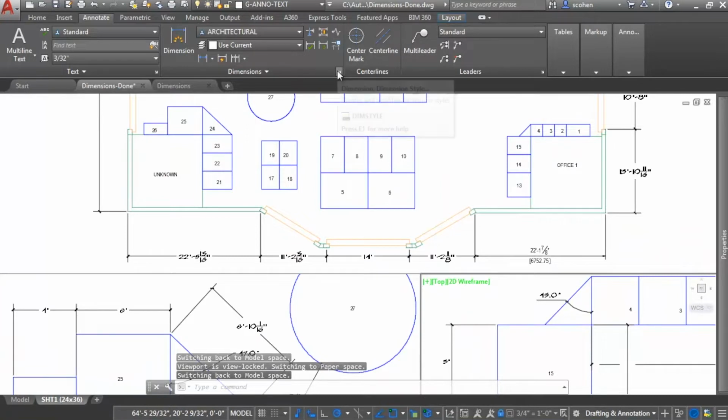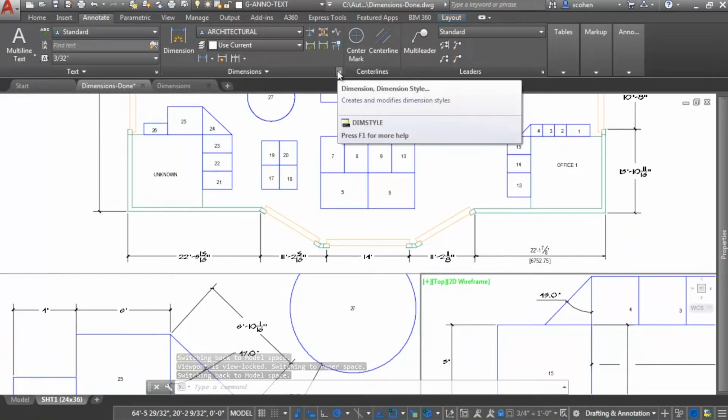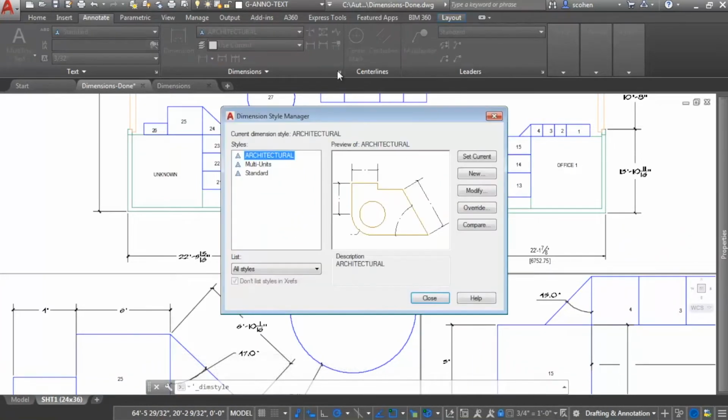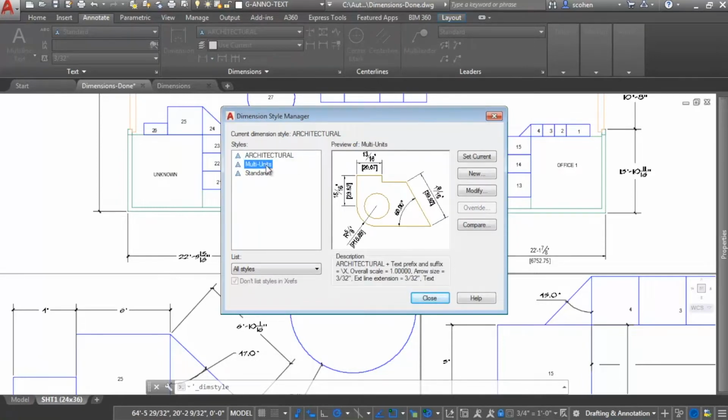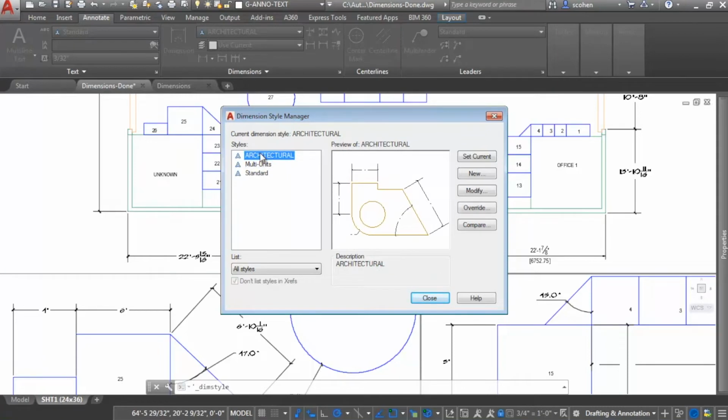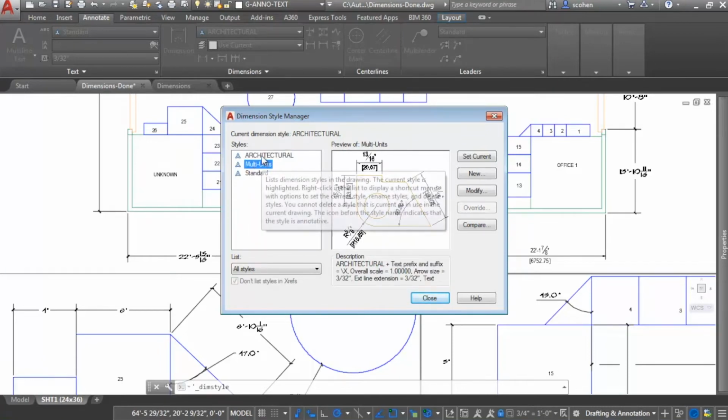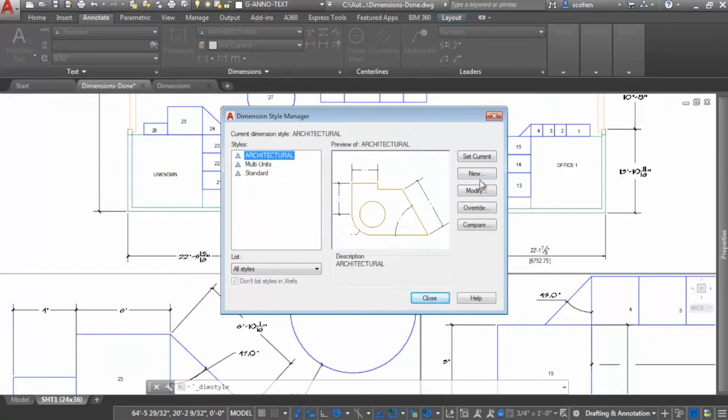Dimension styles are used to manage and automate every aspect of your dimensions. Dimension styles allow you to maintain consistency in your drawing annotations and to organize your dimensions. To automate dimensioning standards at your company, you could add dimension styles to your company-wide drawing template, making it really easy to follow your dimension standards.